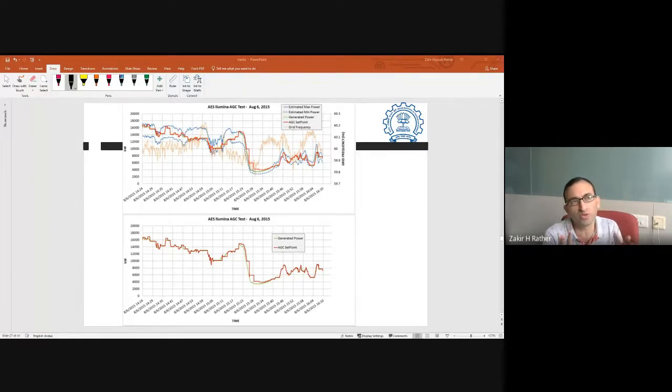When I was talking about the inherent beauty of the synchronous machine in the conventional power system, it is there on the load side also. When the frequency decreases, on the load side, particularly the motor side, be it induction or synchronous motor, their power also decreases normally, depending on which type of induction motor you are talking about, considering their load characteristics. So they also participate in this inertial response or frequency support response. So yes, the load side contributes to the inertial response, and in some cases it has been reported that the contribution of inertia from the load side can go as high as 20% of the total inertia in the system.